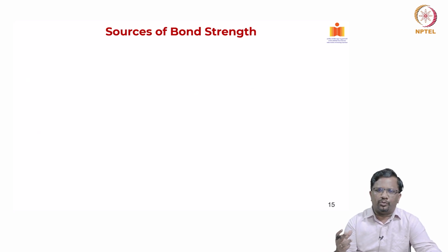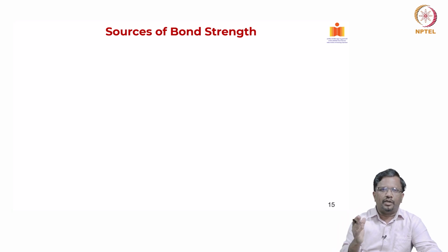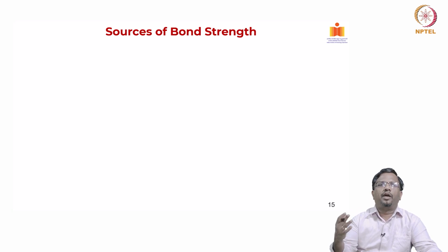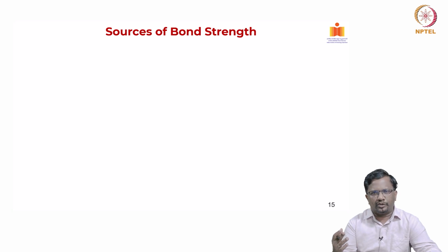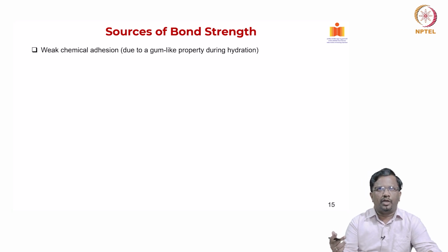Okay, there are two things. One is a bond required to develop that force, which is called the transfer length. The second one is because of the load effects, the increase in bending moment, again you need to develop some additional bond stresses, which are called flexural bond stresses.